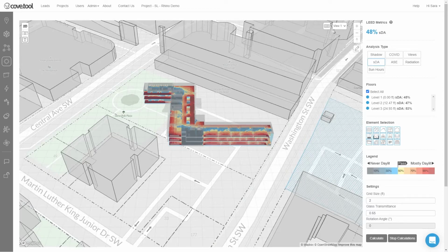Environmental conditions are based on the Tregenza sky dome, constructed from the weather file with 576 subdivisions. To speed up the simulation, we keep the reflectivity percentages, or materiality, fixed with the following assumptions. Floors have 40% reflectivity, interior walls 70%, ceiling and roof are also 70%, and exterior facades, including shading devices, mullions, light shelves, etc., are 50%.